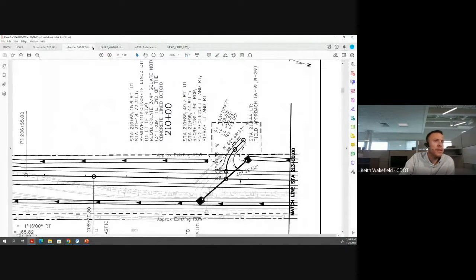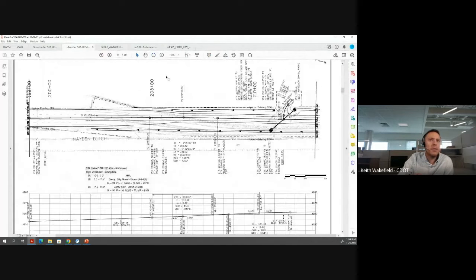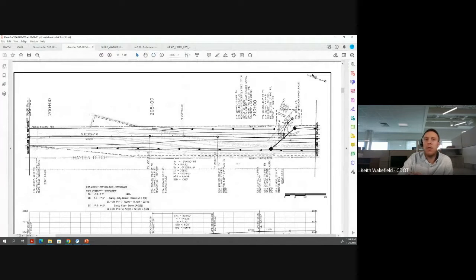So now back to our plan set. Let's zoom out a little bit more. That's what's going on here. We've got our north arrow. The north arrow provides what direction is north, so you can orient yourself around where the road is located. We've got a scale bar at the bottom; typically everything on these engineering plans should be to scale. So if you ever need to measure anything, you've got this scale bar that you can base your measurements off of on the plan sheet.